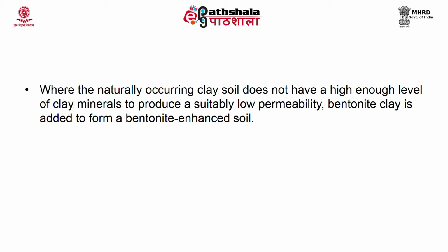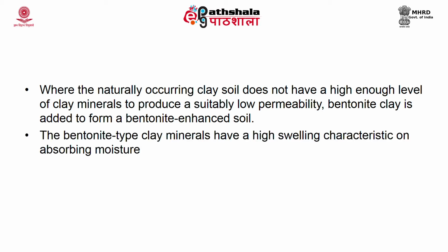So, clay will be mixed with silt and a clay silt liner is made. Here again, wherever the natural clay is not available, in those places you can use a bentonite clay. Again, you can mix it with the soil and a bentonite enhanced soil can be produced, which can be used as a liner material. The property of bentonite type of clay minerals is that they have very high swelling characteristics due to absorbing moisture.